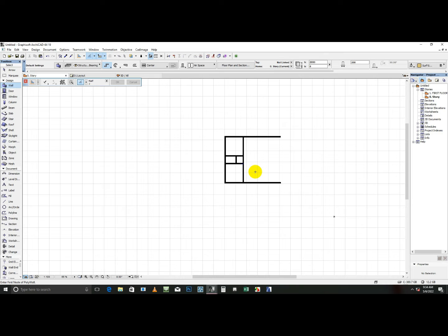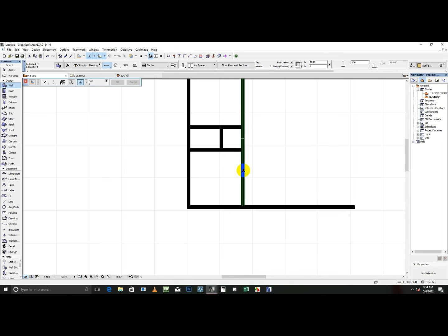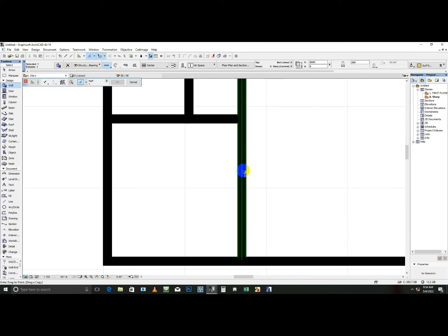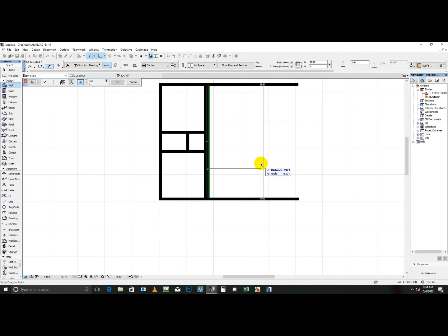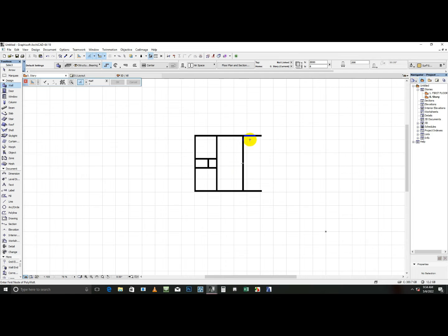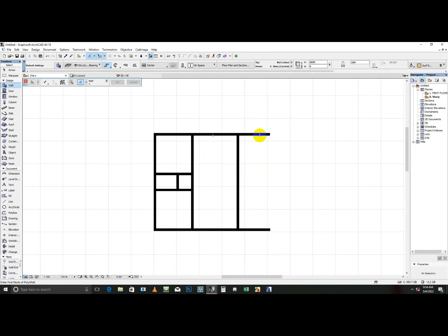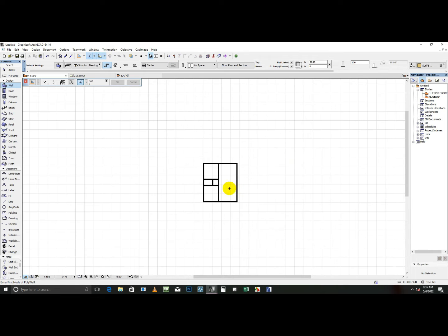All right, so I want a copy of this wall. Control Shift D, click there, Control D for you to feed in the information you want, 3800. All right, okay. So what do I want to cut this? So I can use Control cut, or rather I can come here, trim. I don't want that.